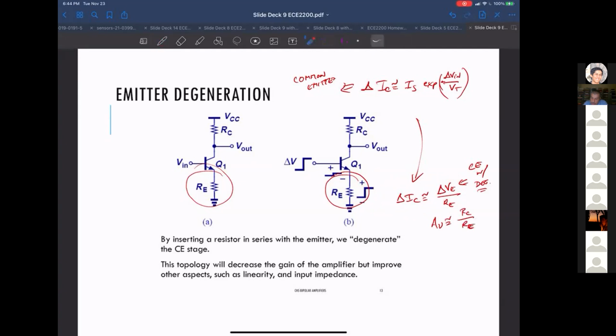We're going to have to give that some more nuance. So your gain is dependent on the ratio of two resistors, and not on G_m R_C, which depends on a current that's difficult to control. The resistors can be made from the same material, sitting at the same temperature, and so on. So your gain can be a lot more controlled.